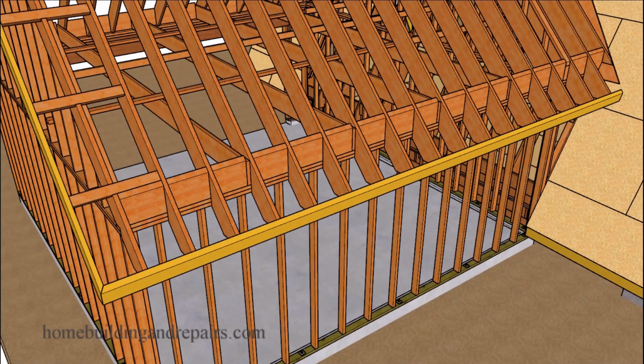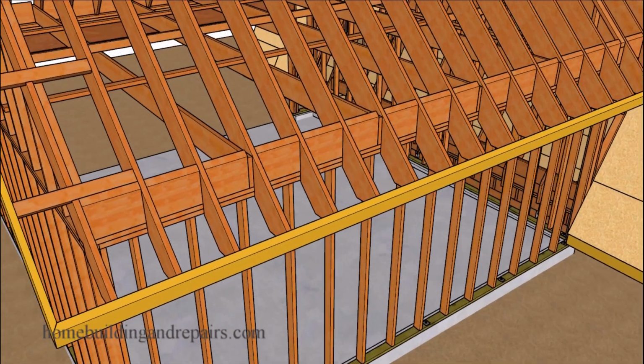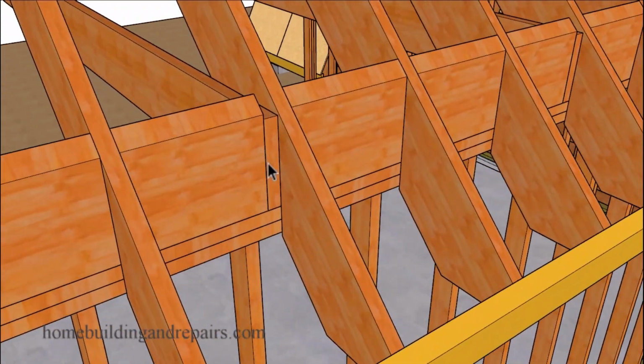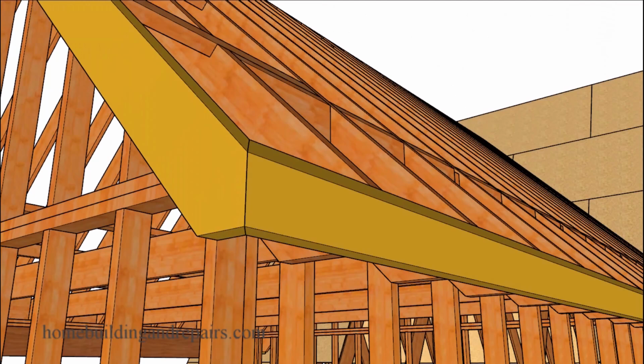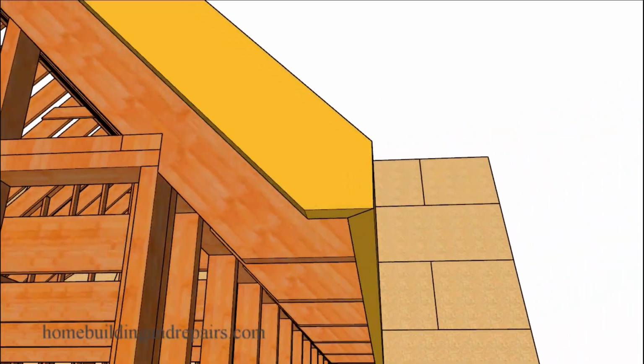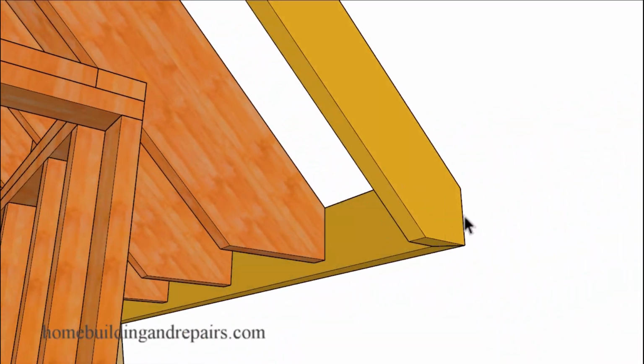Go ahead and take a look at the other fascia board corner. The blocks and how they're going to attach to the rafter tie. You could always run the block past and have the rafter tie sit behind the block if you're looking for a different type of assembly method. And of course, our shaped fascia board. And we're going to have to do some notching here to make this side here blend in with this side here. Going to have to look something like this.